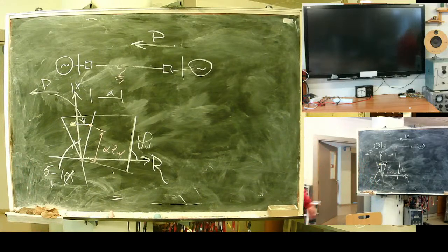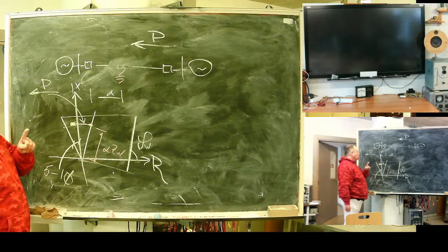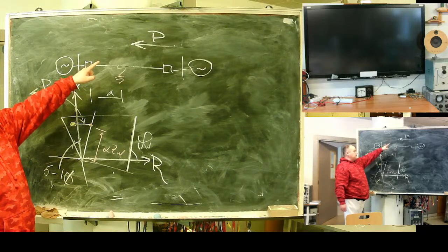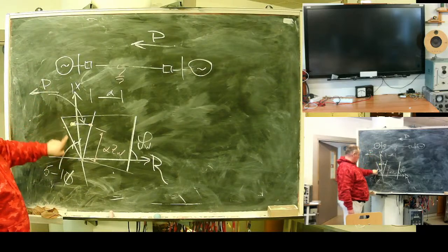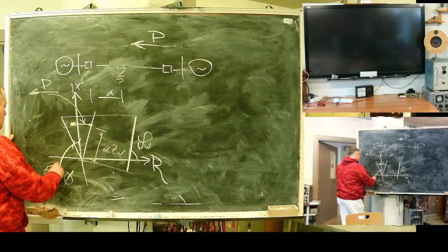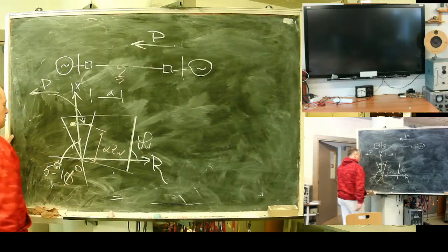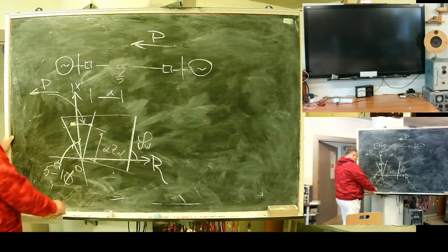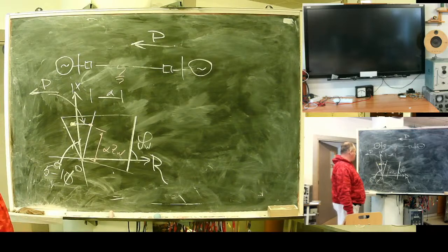But never mind. To prevent misoperation due to power transfer, the phase angle in characteristic, from 5 to 10 degrees, it's needed. Okay, it was a simple part. Now more complex.